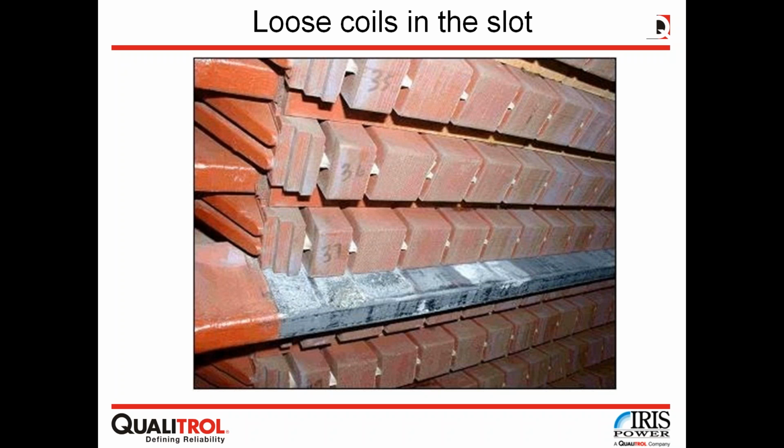Okay. Is this technology, PD and flux monitoring, applicable to lower voltage motors by using different sensors? Well, when I said at the beginning what is AC and what is HV, for us HV is higher than 3.3 kV. If it is lower than 3,300 volts, the potential for both problems is very remote.